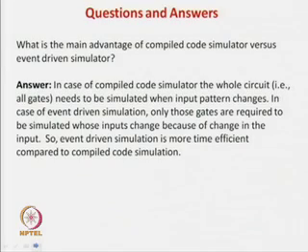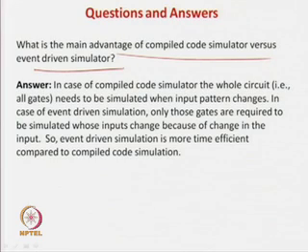So, we are asking what is the main advantage of compiled code simulation versus event driven simulation. Here, what is the answer? We have already discussed many times, for concurrent fault simulation, deductive fault simulation and normal circuit simulation. In compiled code simulation we convert the circuit into a program and you execute it for a pattern. Then you forget everything, and if you change anything, you have to redo everything.